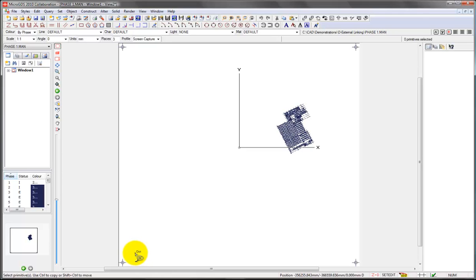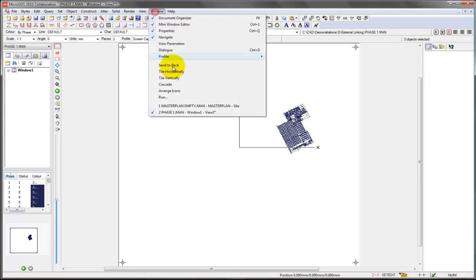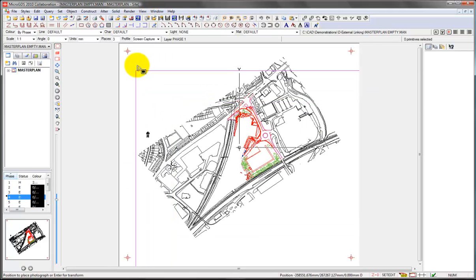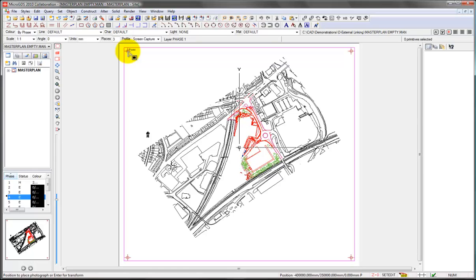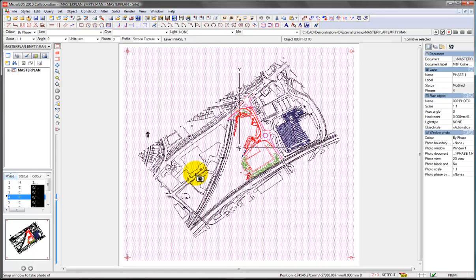Master plans. So what we'll do is we will take a snapshot, a photograph of that particular view, and if we just snap onto the point where the registration marks cross here, switch back to our master plan view and snap onto the same position in the registration mark there, and that superimposes a linked view from that original file. It doesn't copy the data from the file at all. This is just an external reference via this thing called the photo to that file.